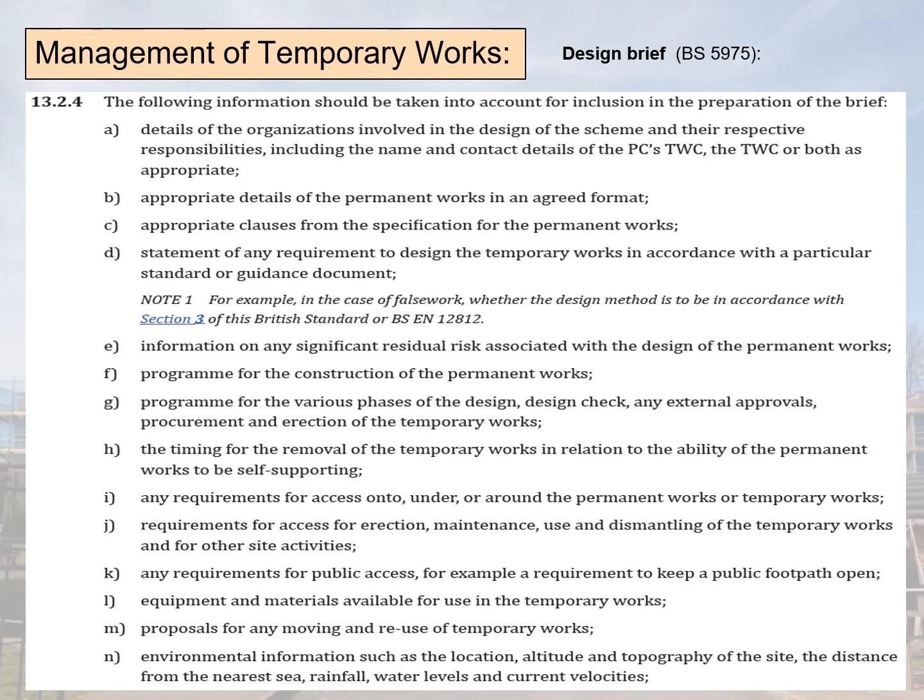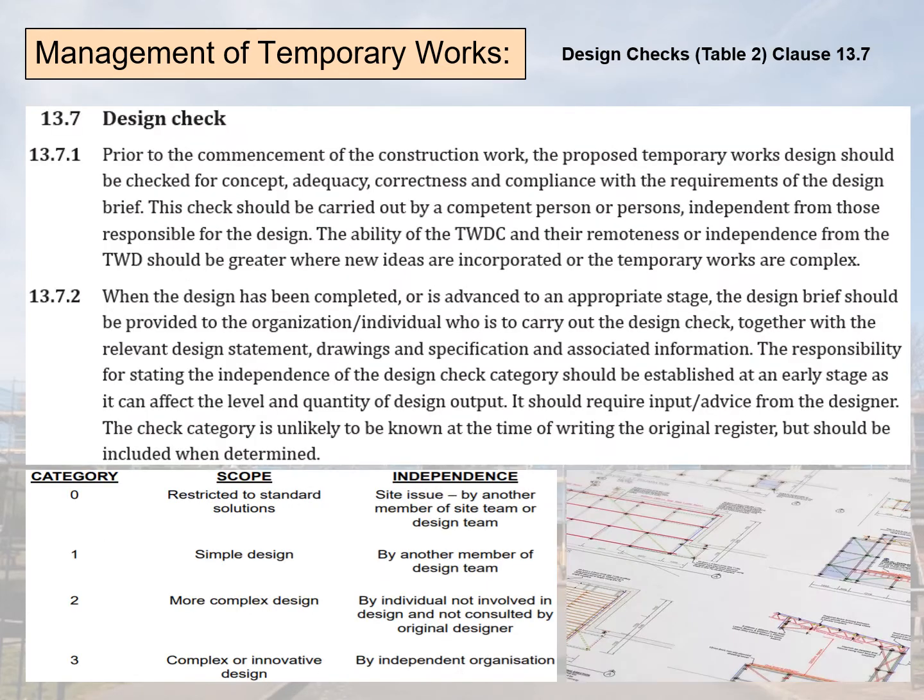Considerate contract briefs and other engagement with local stakeholders. Once the design has been completed, design checks are required to be implemented. Prior to the commencement of any construction works, the proposed temporary work design should be checked for the concept, adequacy and correctness and compliance with the requirements of the design brief. More details of these are outlined within BS 5975.